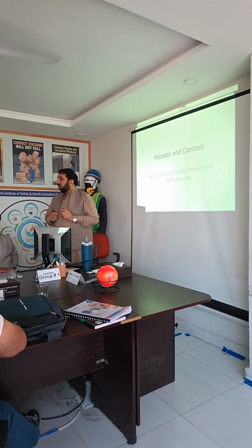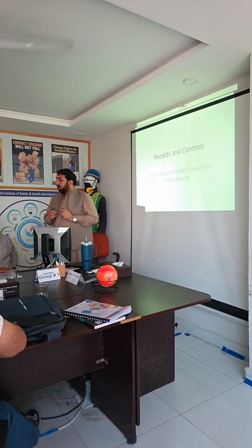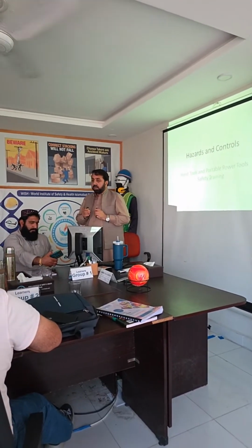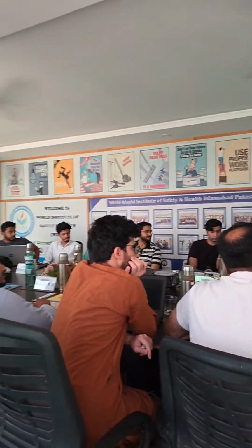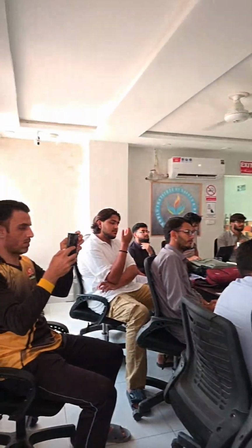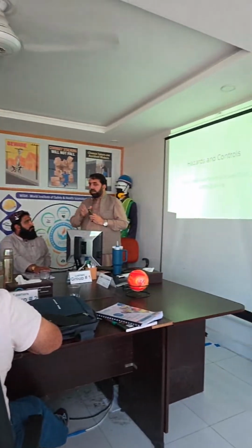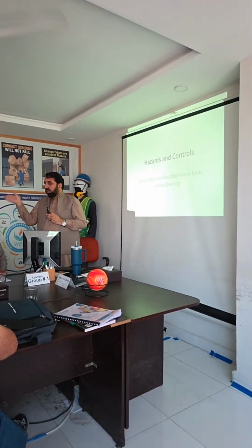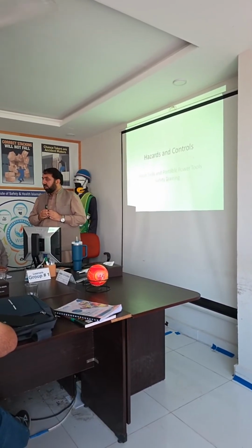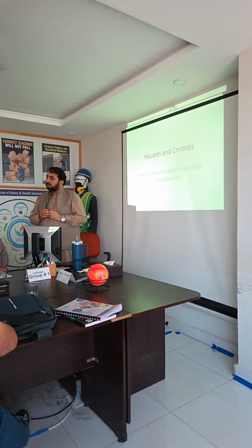Why is this requirement there? Because if you don't know about the hazard and risk of it, like in our street, one of the workers was using a cutting grinding machine without a guard. When the disc broke, it went directly into his eyes. So power tools are very, very serious, especially the handheld tools and the power tools.